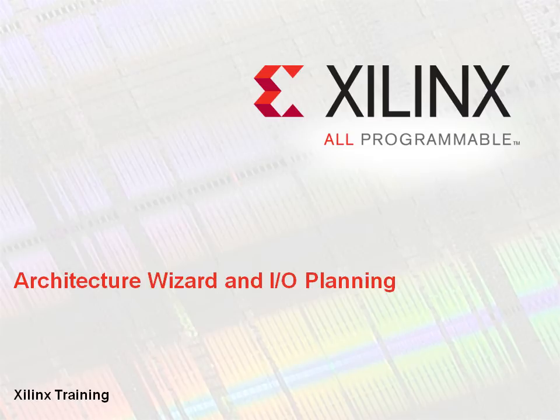This module is about the architecture wizard and I/O planning functionality incorporated in the ISE software. This module introduces the architecture wizard, which is used to build your FPGA's clocking resources. This utility builds an instantiation for each customized DCM or MMCM component that you add to your design. This utility makes it easy to determine all the clocking features and select the options that you want in your design. It also provides error checking so that you don't build a component that will not work properly in your FPGA.